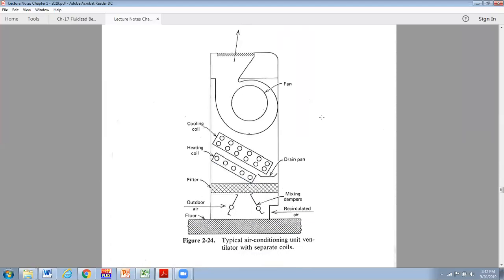This is the unit vent, which is what we do have in the classroom. Very similar to the fan coil. They're showing 2 coils in here, a heating coil and a cooling coil, which we have in the units in Brown Hall. They don't run water through them at the same time. They're not supposed to anyway, unless the coils are leaking through.